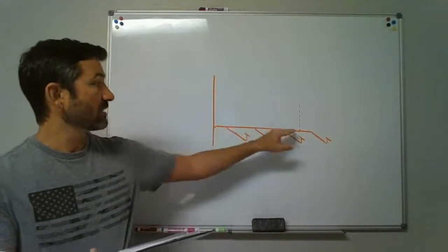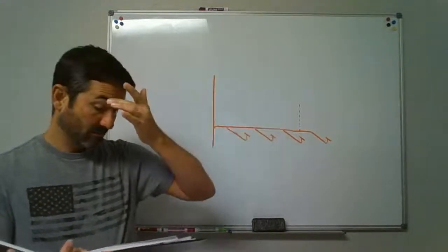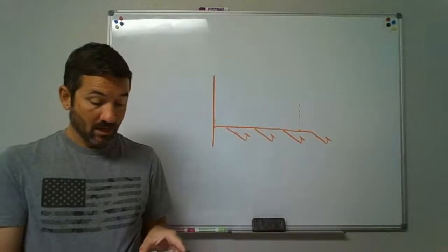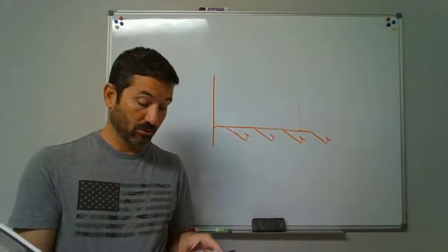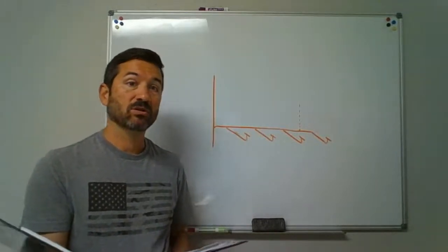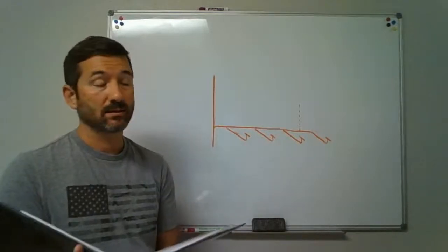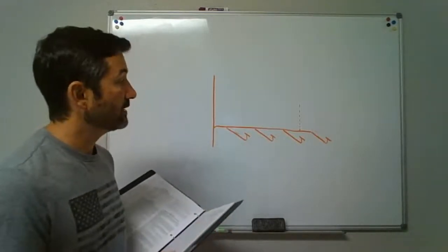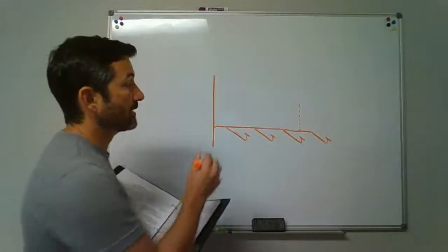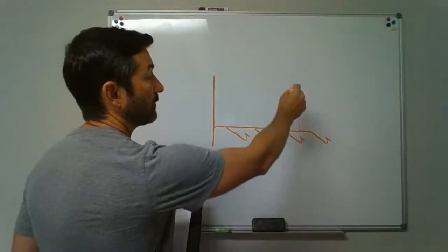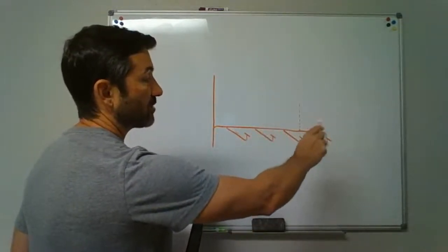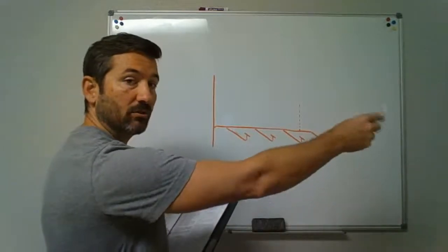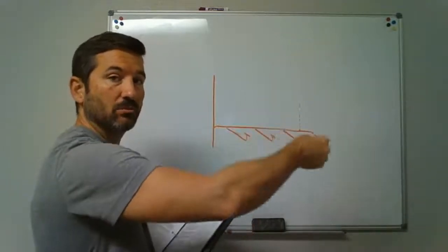So all of this is considered the vent for those. It does tell you that you can have multiple circuit vent branches. So you just say, well, how about if I had more than 8? Well, you can go more than 8, but then you're going to start counting again when you're between 7 and 8. You'll put a vent up, and then you start counting again, as in 1, 2, 3, and you can go another 8 and put one between the two most upstream.